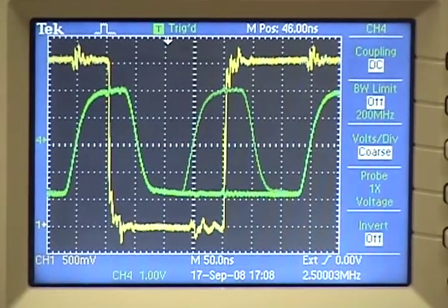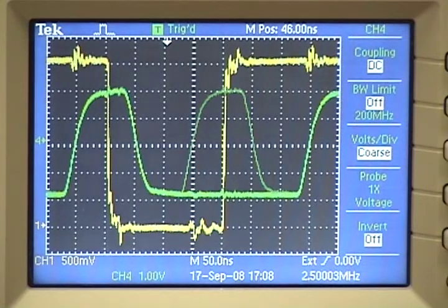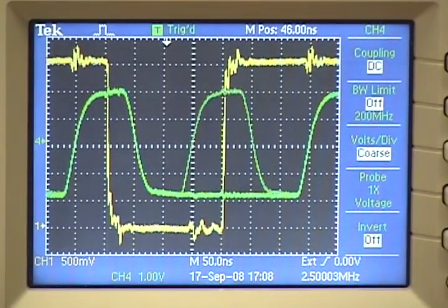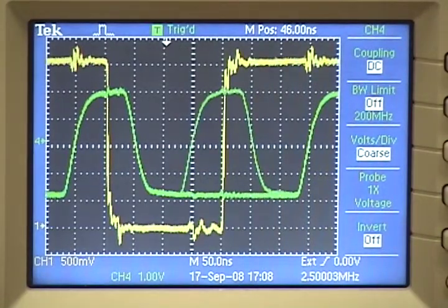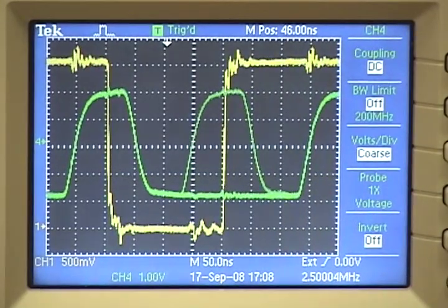The system also has monitor outputs, which allow us to see the actual analog waveforms that we are digitizing and the point in time when we are sampling. Shown here on the oscilloscope, the green trace is our video stream and the yellow trace is our sampling clock. The scope shows 1 pixel period of the video waveform. The video signal has a constant high region, a constant low region, and a region that is intermittently high and low. This is the region that is flickering on the oscilloscope, and it is the place where we want to sample the video. This is similar to a typical CCD output that has a reset feed-through, a reset pedestal, and an information well.